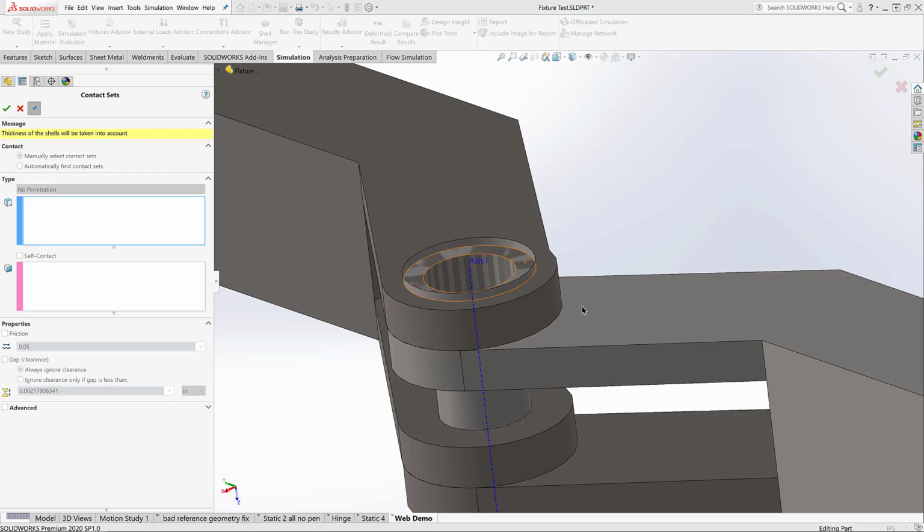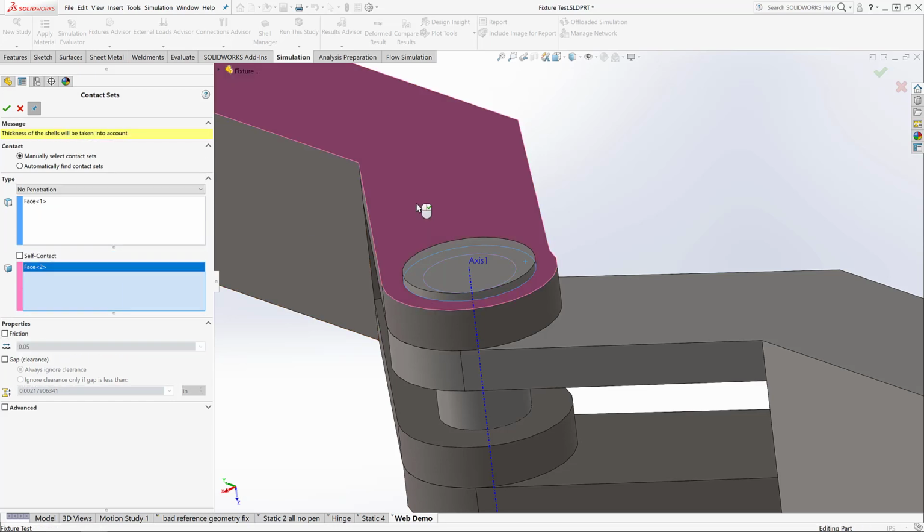And there we go, the interface of that first little nut. And we are going to make sure that doesn't pass through this face. And I'm going to say no penetration contact. And remember when I said if you have frictional constants here, you can apply them, especially with respect to your model, to your data set. Since I'm a physics nerd and we do all of our experiments without friction, we're just going to keep it simple and not include friction.